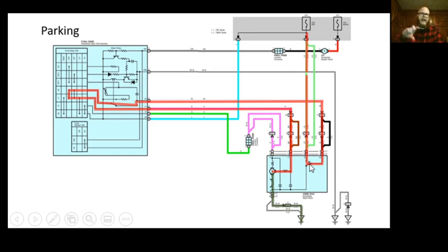There's actually something mechanical that physically pushes the switch one way until the motor comes to that sweet spot and the switch has pressure released from it, for a very, very small amount of travel. So while the wiper motor is spinning and the wipers are wiping back and forth, this switch is connected to this circuit the majority of the time. When it's turned off, obviously, the switch is going to be connected to ground.